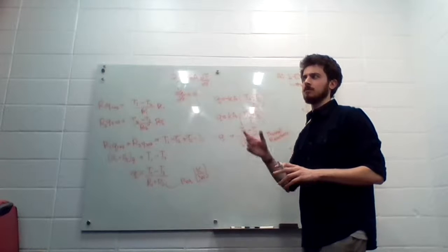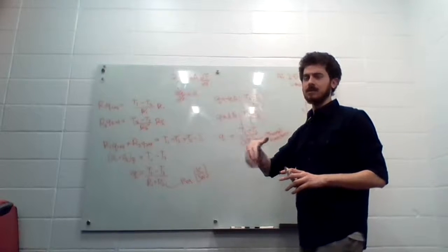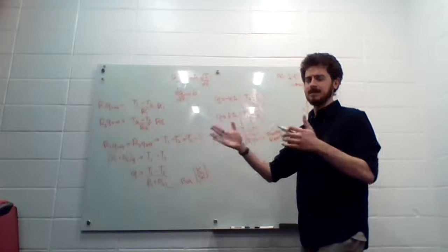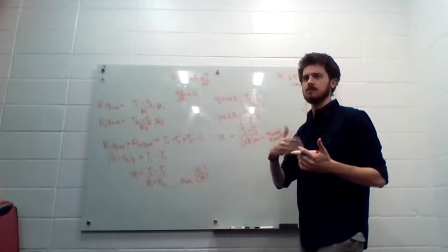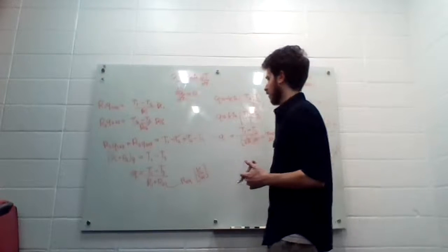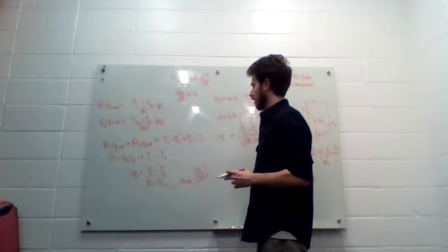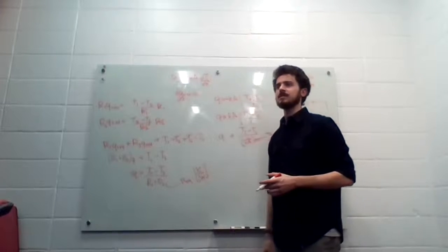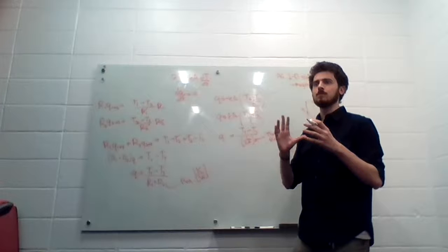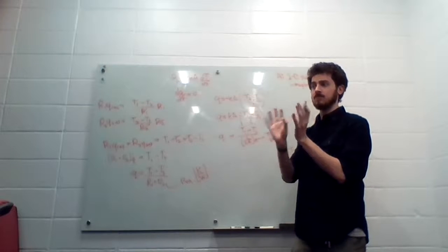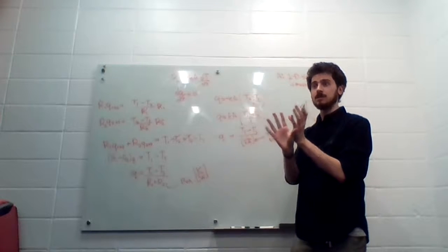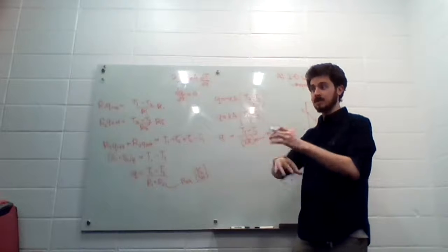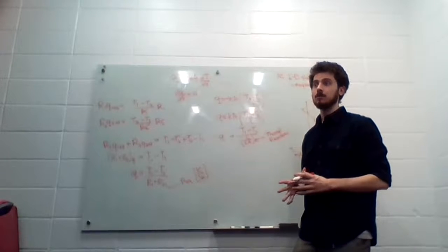That expression takes out area. Also, when you say R20 in the United States, you're using imperial units, like BTUs and feet. The concept is the same, that basically you've come up with some kind of all-encompassing single value that describes the heat transfer properties of the wall independent of the temperature, and you can use that.